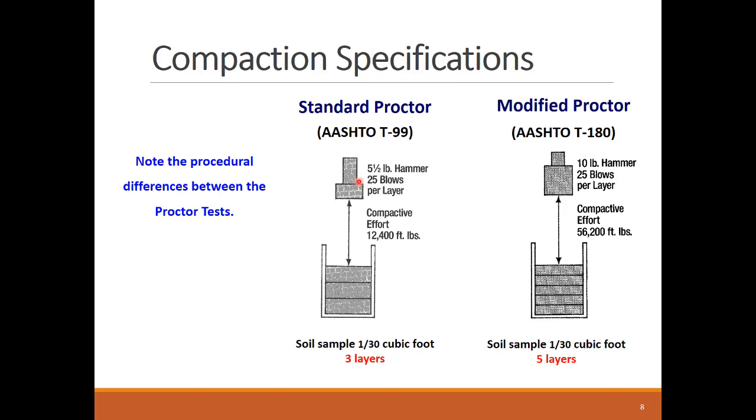For the standard Proctor test, the soil is placed in a cylindrical steel mold in 3 equal layers, where each layer is compacted using a standard hammer weight that's dropped from the same distance. After all soil layers are placed and compacted, the dry density is measured. This process is repeated for different moisture content to obtain the compaction curve and identify optimal moisture content.